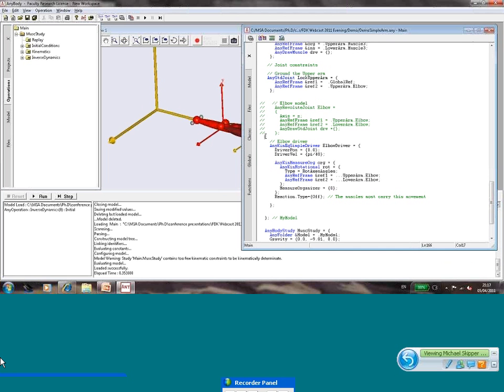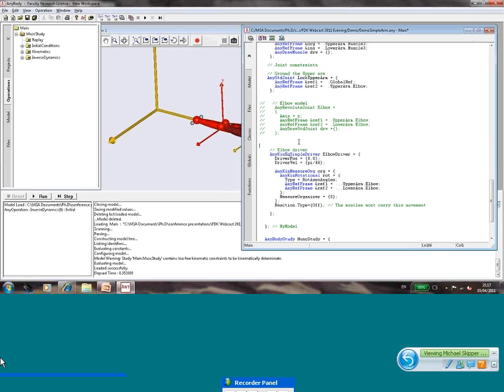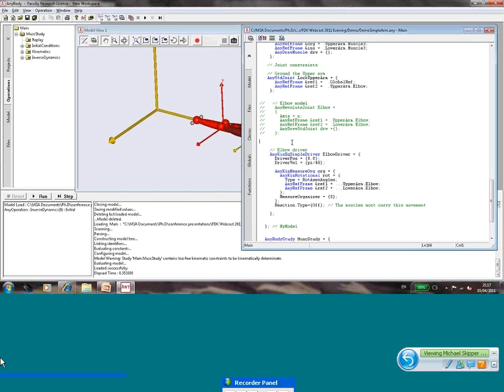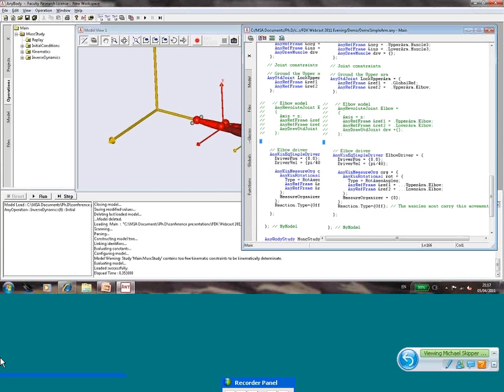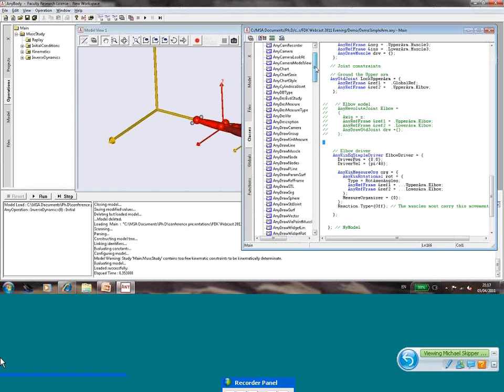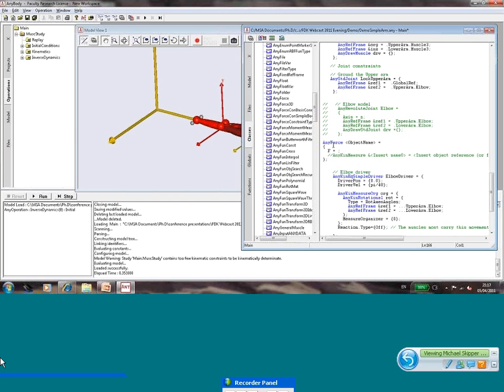And what I would like to do is put in linear springs between these 2 points that we had from before. And then I would like to tell the system that it should compute the quasi-static motion, or the force-dependent motion, in these degrees of freedom. So the first thing we need are our springs. I go to my class list here, then I can get a list of all the classes within the system. And then I find AnyForce, which is the general way of putting in a force in any script. And I will call this one, let's give it a name, I'll call it spring 1.